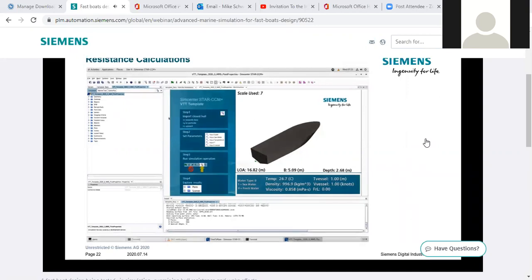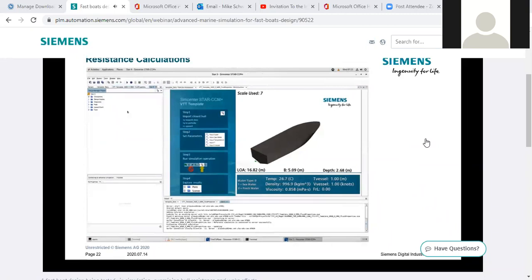So here's a walkthrough of how it works. So we have our existing single point simulation. We right-click. We create a Design Manager project, and then we just create a new design study. So in this case, we want to run a sweep, but of course you could choose from CAD robustness, an optimization, a design experiment, or just a manual input of runs.